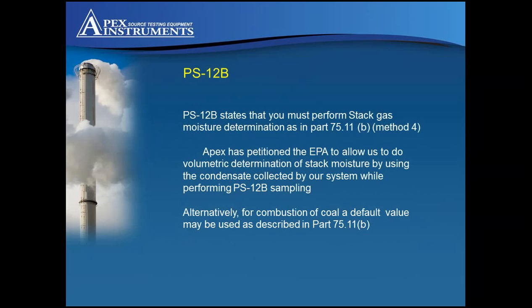Another aspect of PS12B is you're required to record moisture. This can be done either from a Method 4, which you should already be doing under Part 75. However, Apex has petitioned the EPA to allow us to do volumetric determination of stack moisture by using the condensate collected during the sample run. However, this has not been approved yet, but we're working on it. This alternate has been approved to be used on Method 30B.